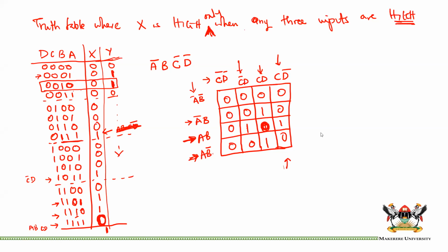All right. Does arrangement matter, A, B, C, D, or D, C, B, A? Actually, it does not matter how we arrange our truth table here. But when we are extracting the information to feed it in the K-map, make sure that you are doing the right thing. Perhaps it is easier to have A, B, C, D, because that one just maps nicely into the way these statements are written. But even if it is DCB, it doesn't matter, just make sure you are picking out exactly the correct information.